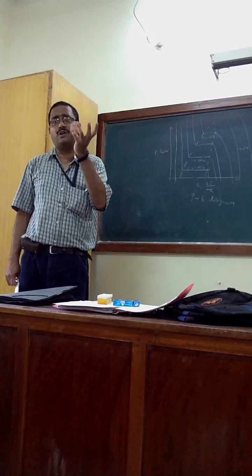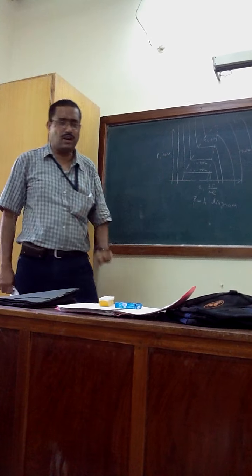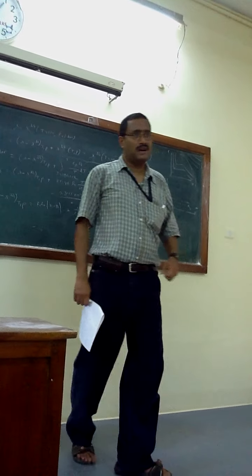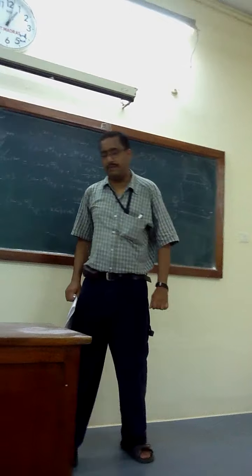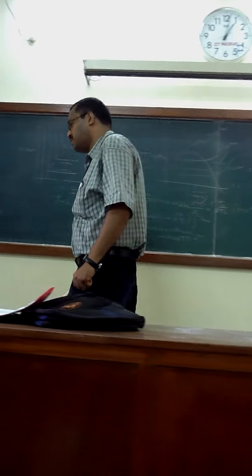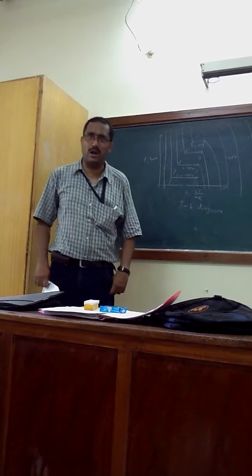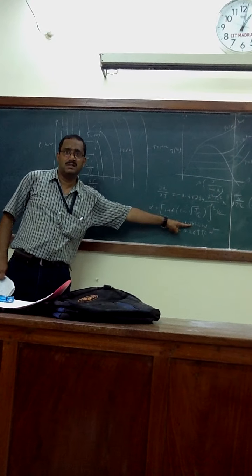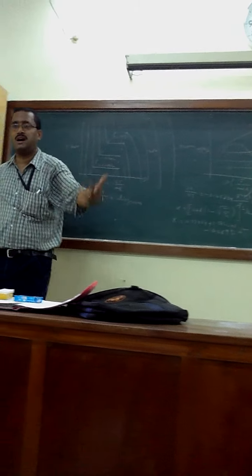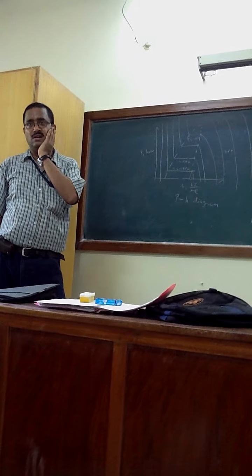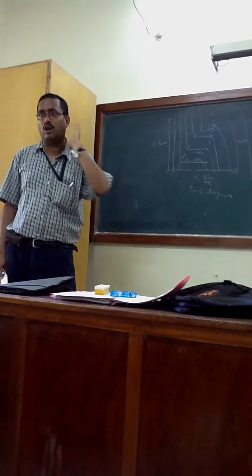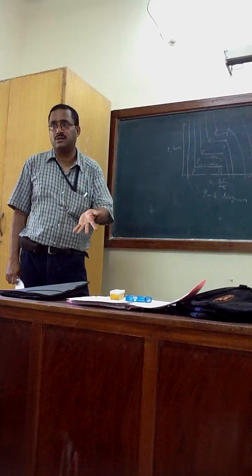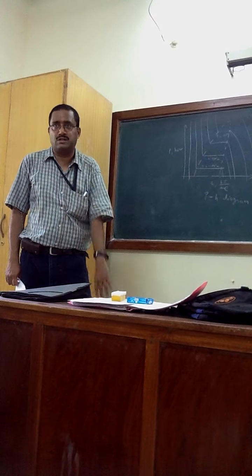It depends on molecular configuration, how the polarity of the molecule. So the real gas polarity matters. Attraction, repulsion, I showed long back, how the Van der Waals equation of state has been corrected based on the polarity of the molecules. For that purpose we have omega. How the role of omega is, that we don't know. Experimentalists will give the data. That's why we need experiments. If you compare, you can say, okay, Van der Waals is having a lot of deviation, Peng-Robinson SRK is not having much, so of course we'll be going for Peng-Robinson SRK. That's the topic of research.